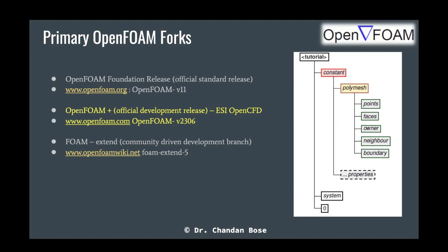Just to tell everybody who doesn't know, OpenFOAM has one of its own meshing utilities. It's called blockMesh, by which we can easily create structured meshes. And the dictionary file for creating the mesh, if we use OpenFOAM to create our mesh, is called blockMeshDict, and that will be located within the system folder. Correct.